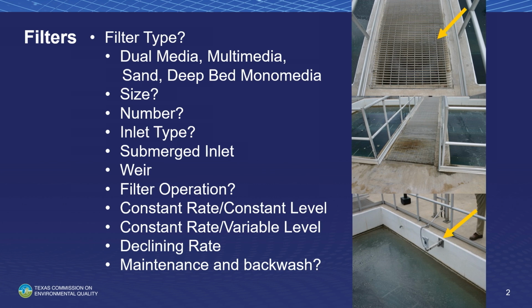When you put a turbidimeter in there, you've got to take the water out of it and put it somewhere. It's got to go to waste. Well, these folks had tied that waste line straight into a sewer line, which is not right. There should have been an air break in it anyway. But they went down to do maintenance because their turbidimeter was giving them crazy readings, jumping up and down, and then it would settle down and read right for a while, and then start jumping up and down again, and they couldn't figure out what in the world.